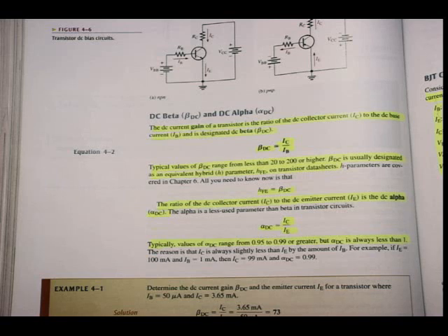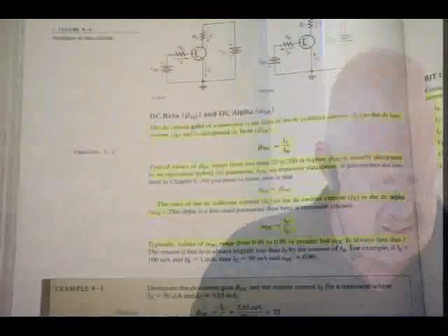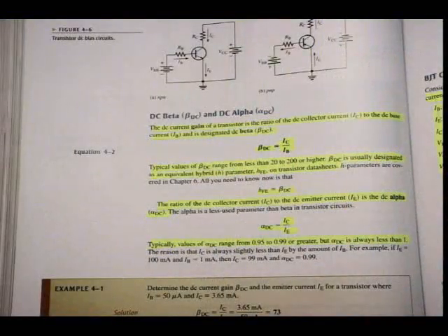So what can I see? The current IB is very small in comparison with either the collector current or the emitter current. But I can see that the emitter current is the largest, so by the magnitude of IB, it will be larger than IC. But actually, IB is so small that in some cases, as you will see later, I will assume that IC is equal to IE to do some of my calculations. So what I can see from this formula, beta DC is equal to IC divided by IB.